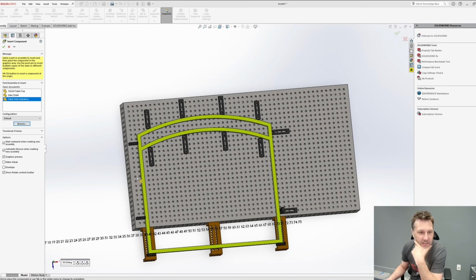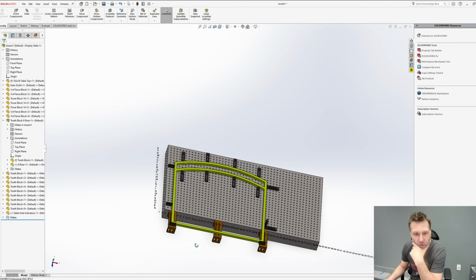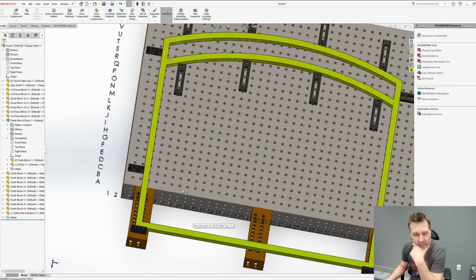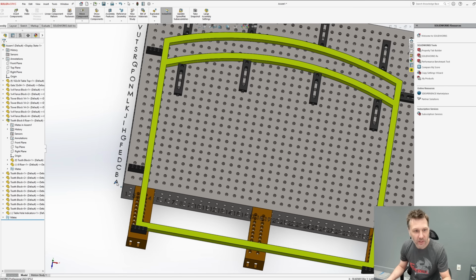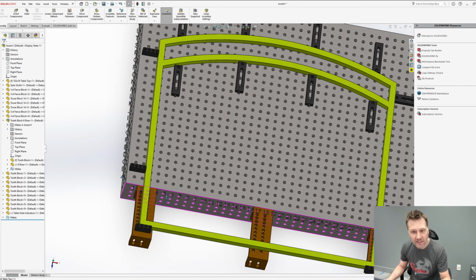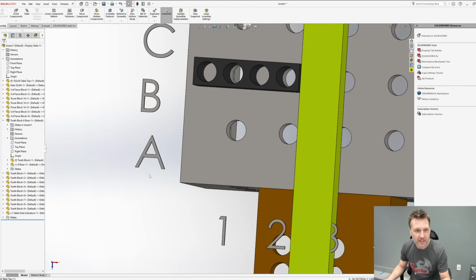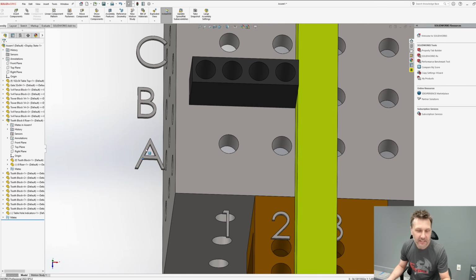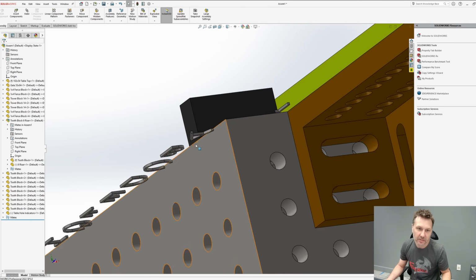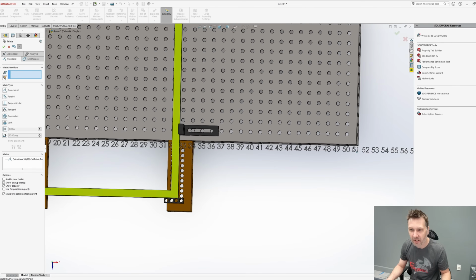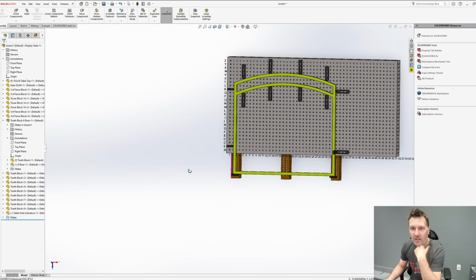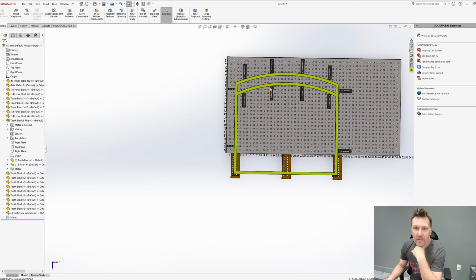And so in SolidWorks, it's always kind of tricky to lay the holes out. If you put hole layout in the table, it really bogs the machine down. So what we've come up with here as a team is we just created our own little part, which is these holes. Looks like this. If you get real close on them, they're just extruded text. Let me go to the bottom of this and mate it. Okay, so now all our holes are laid out all the way out to 50. Yeah, looks good. And now we know every hole. Now we just need to know the measurements.